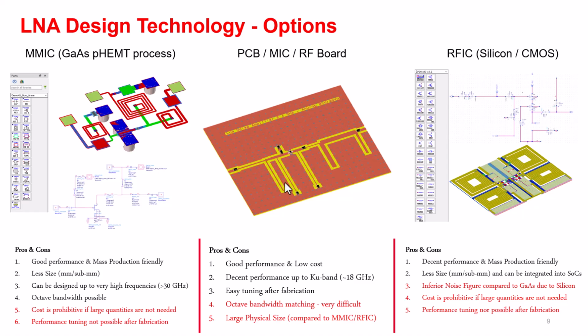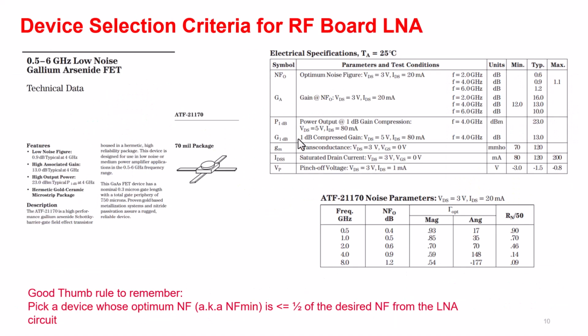So in this webinar we will focus on RF board since it is like every man's tool. However, the concept you are going to learn is equally applicable whether you are doing MMIC or RFIC kind of designs. Now, if you are doing a PCB design, you have to first find a low noise device which you can use in order to design your LNA.